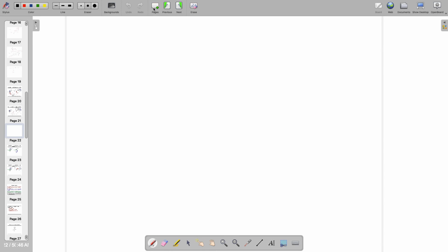So now, what if I'm making this kind of circuit? One more time, I'm just solving for you without drawing any small signal model. So this is Vin, this is Vout, this is M1, and this is RD. I know looking into this one is going to give me 1/gm. Very nice. But here at the output side, there are two branches, and this is also ground. If there are two branches, they are in parallel.